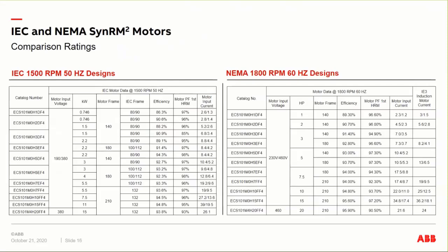It's kind of an eye chart, I know, but just to line up IEC ratings with NEMA ratings, we're at a lower voltage on IEC, lower base speed, 1500 at 50 Hertz, a little bit more current draw, but we're still hitting the IE5 efficiencies here. And that's because we were already at IE5 plus. So they're a little lower efficiency than the NEMA. And that's just strictly because you're running it at a reduced voltage and higher current draw.